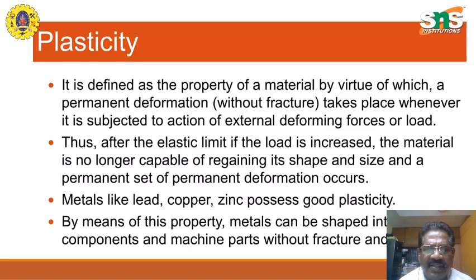Thus, after the elastic limit, if the load is increased, the material is no longer capable of regaining its original shape and size, and a permanent set of deformation occurs. Metals like lead, copper, and zinc possess good plasticity. By means of this property, metals can be shaped into components and machine parts without fracture.